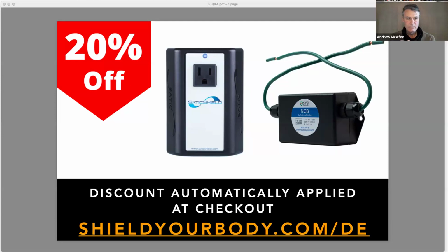There is a diagnostic that I do when I'm trying to find the lowest electric field possible, which is when I install a double pole outlet switch. Basically, it's a light switch that will cut the hot and the neutral at the same time, which is allowed by code if it's off at the same time. You can't cut them at different times. When the hot and the neutral go down, there's less electric field.